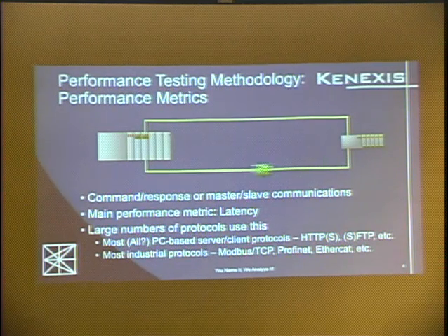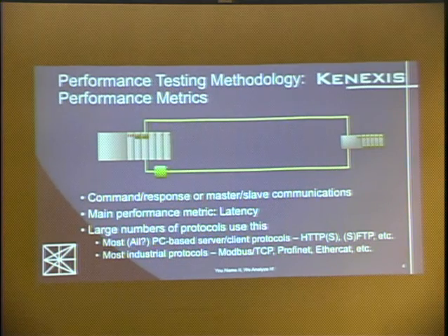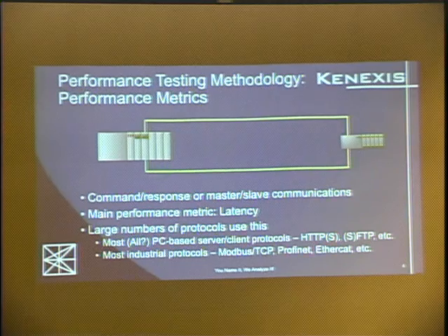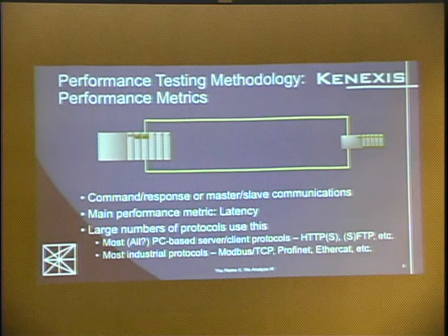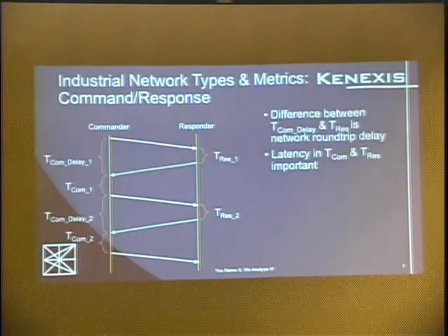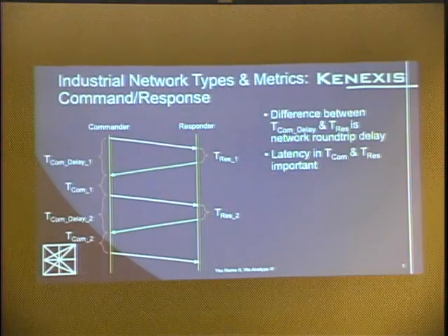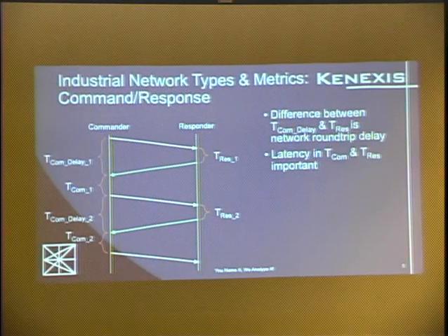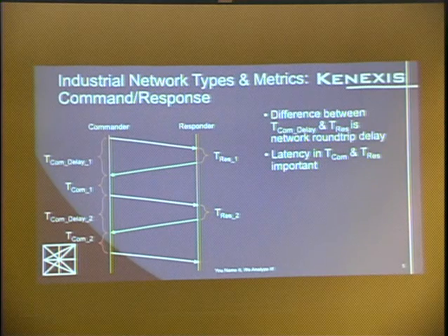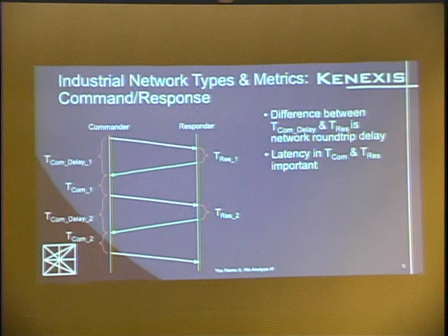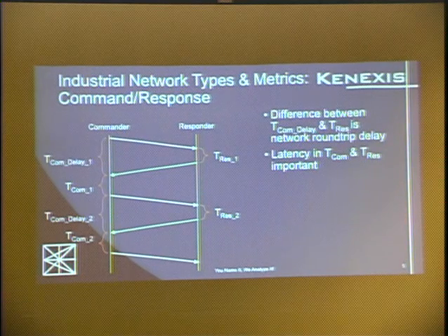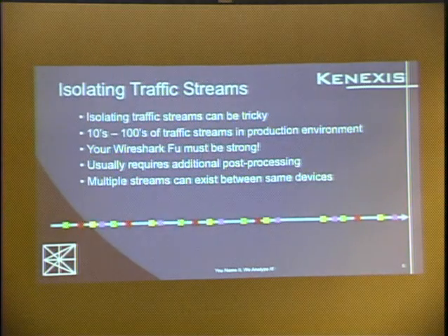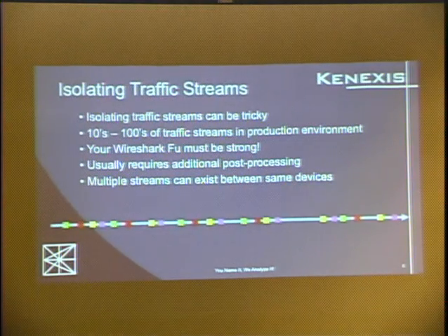In this case, you need to make sure that the response is within a certain amount of deterministic time. If it isn't, then that's going to send the whole system off as well. Again, you've got another timing diagram. The response delay on the responder side is what's really important here. Generally, the commander is a higher power device. It's going to have more horsepower to it. It's not going to have the same sort of problems with communication frequencies and speeds. Okay, that's one device talking to another device.